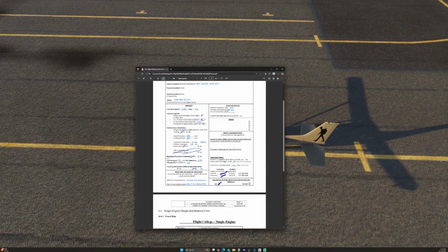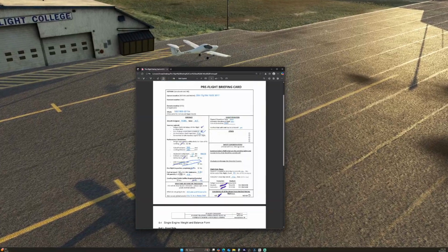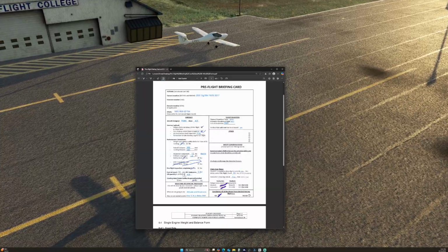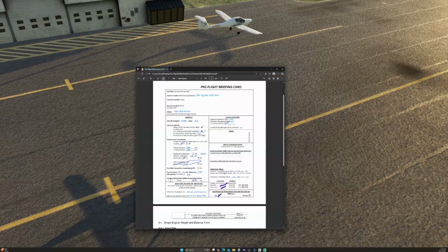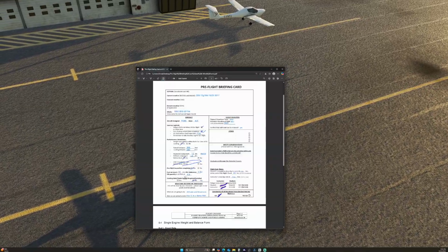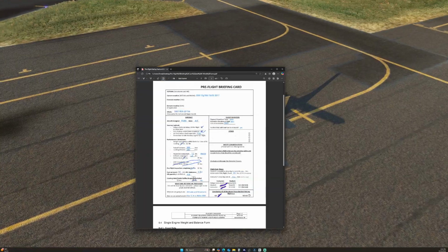The next item is the pre-flight inspection, which has already been completed before the stream. Fuel on board is 56 US gallons, and that gives us an endurance of about 5.5 hours worth of fuel. Oil quantity is verified at 6.6 quarts, and that's simulated here in the sim.